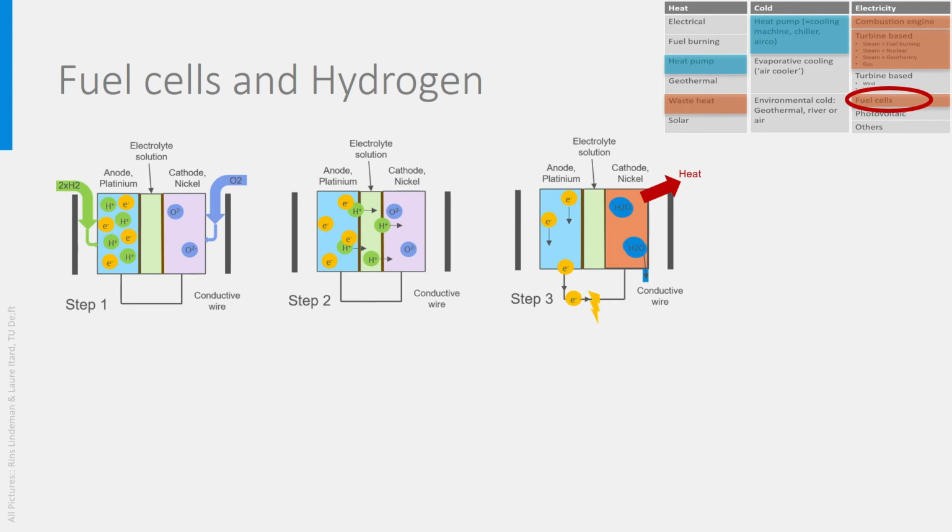We touched on it in previous slides. Hydrogen, H2, is just a fuel among many others, and most boilers, combustion engines, gas turbines and steam turbines could be powered by hydrogen, with the giant advantage of no CO2 emissions during combustion, just because there are no carbon molecules at all. Of course, some changes must be made to the burners, but that is doable.